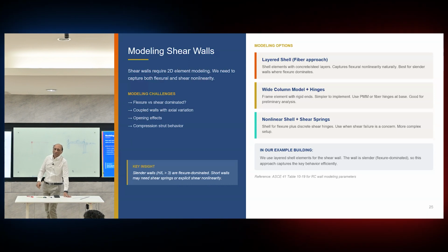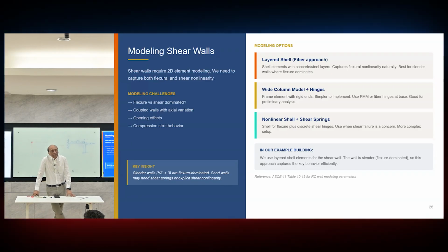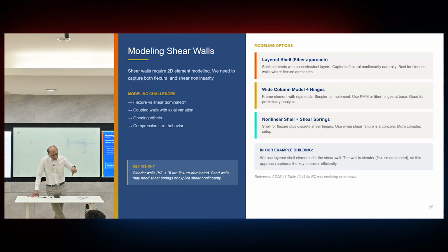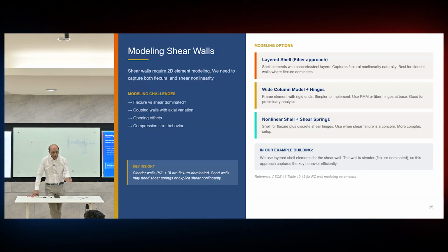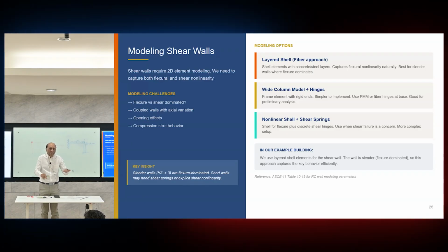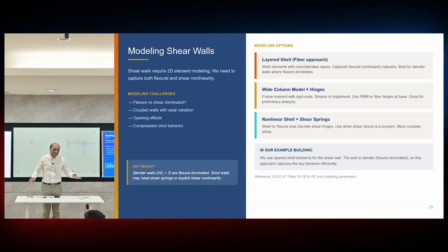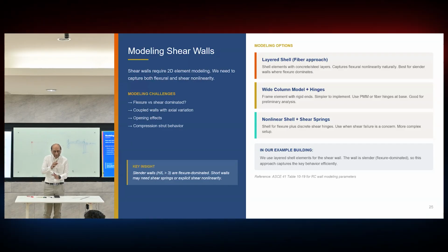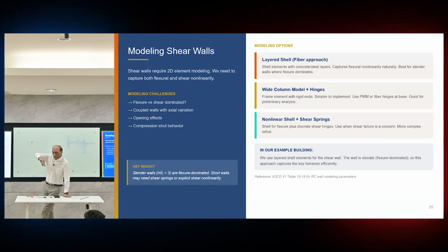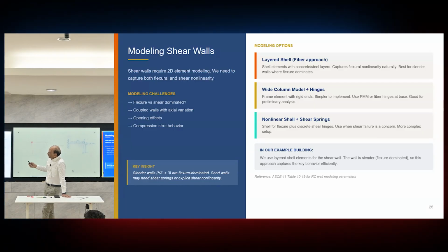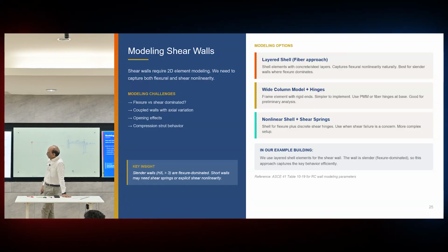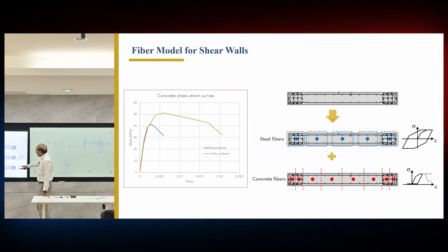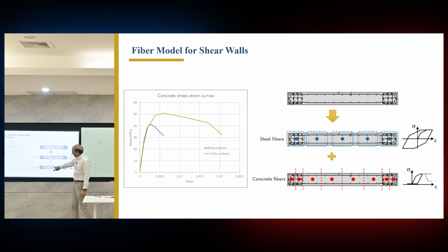Or they can use what is called the multi-link vertical elements. So it's like a fiber hinge, but it is not combined back into the section. It is kept as a cross section with the physical dimensions, assuming that they are all moving together, deforming together. So that was developed many years ago, and people still use that. So in case of the fiber model, you specify the fibers.